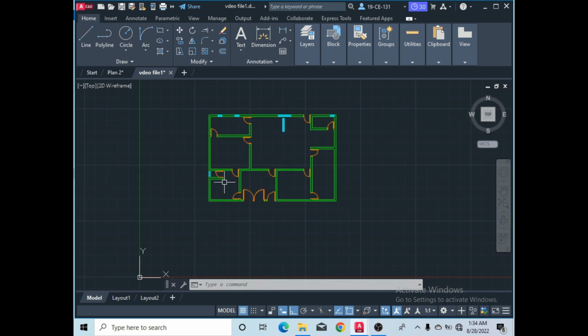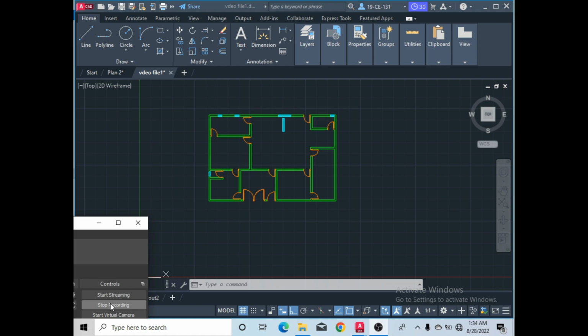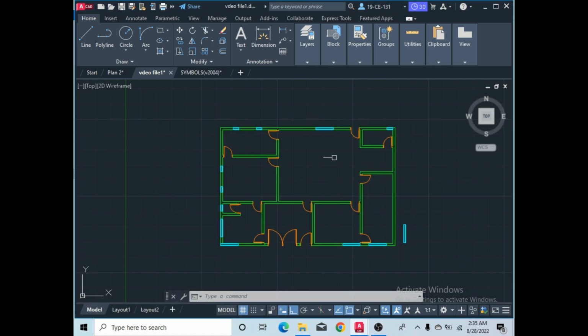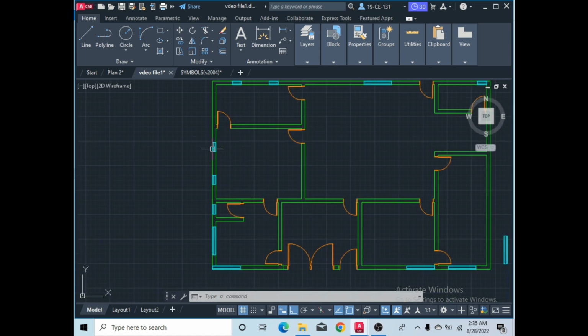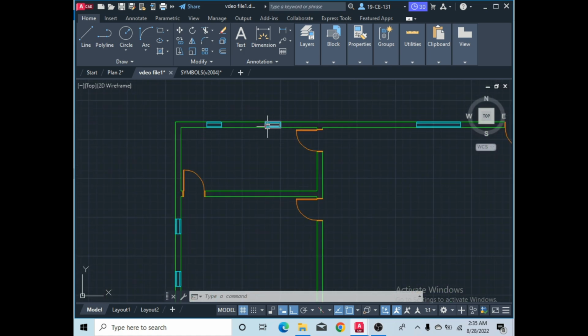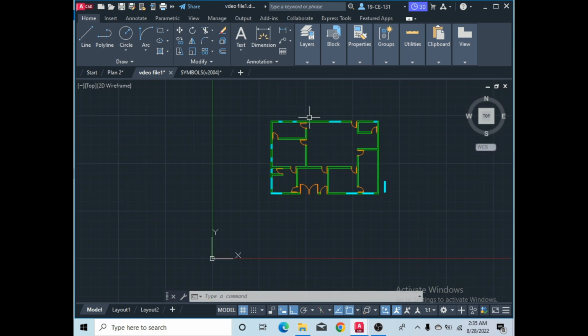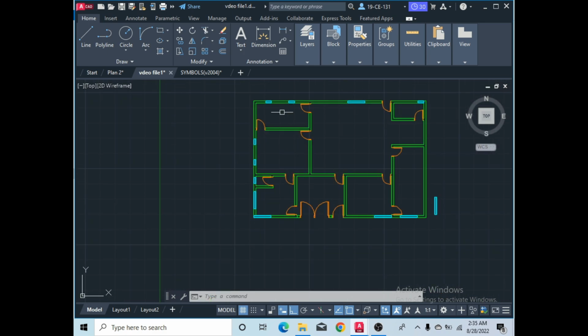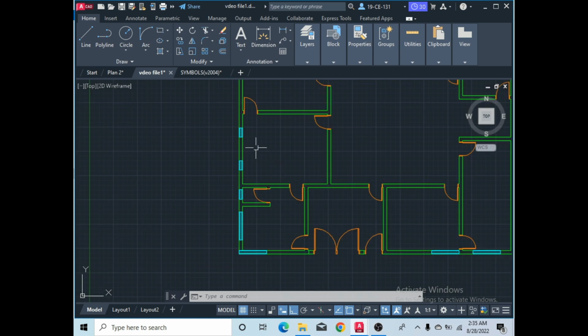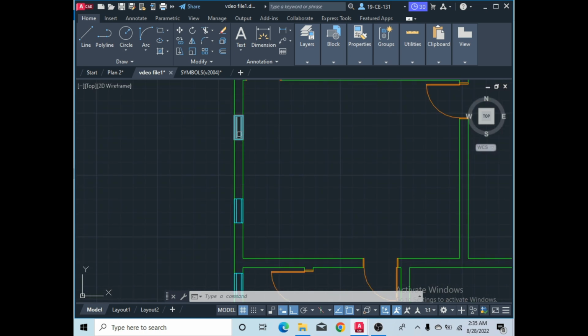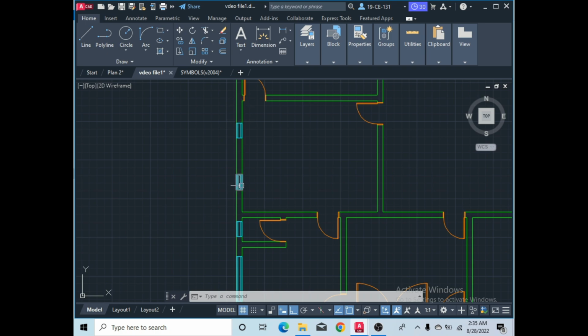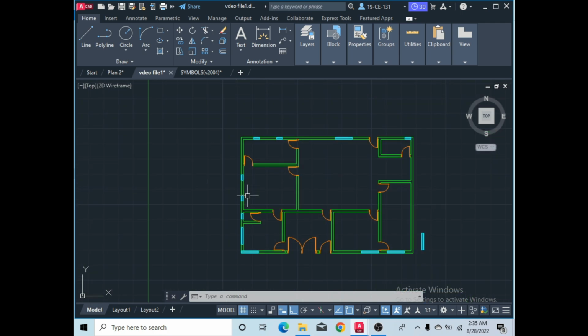So now you should set this window here in this corner, and in this corner one in here, one here, and one here. So we should put all these windows. Let's take a copy of this, or any which is required, simply copy it and paste it there and set that wall. Let's say I set this 3 feet away from this corner, and I set this 3 feet away from this corner, and this window is 3 inches from this side.